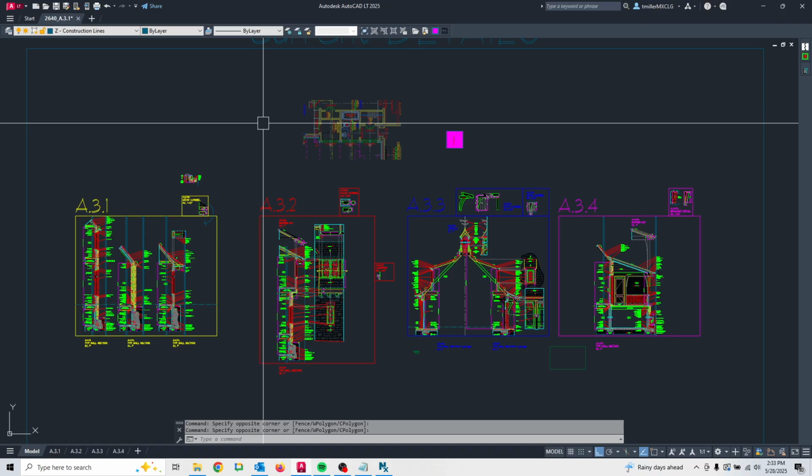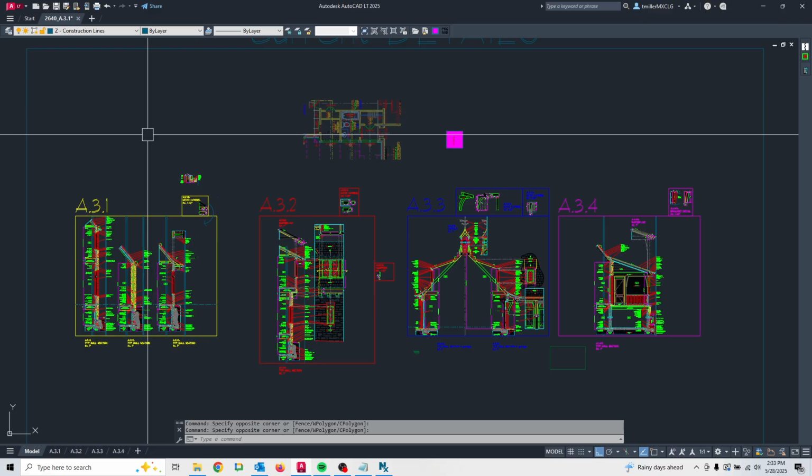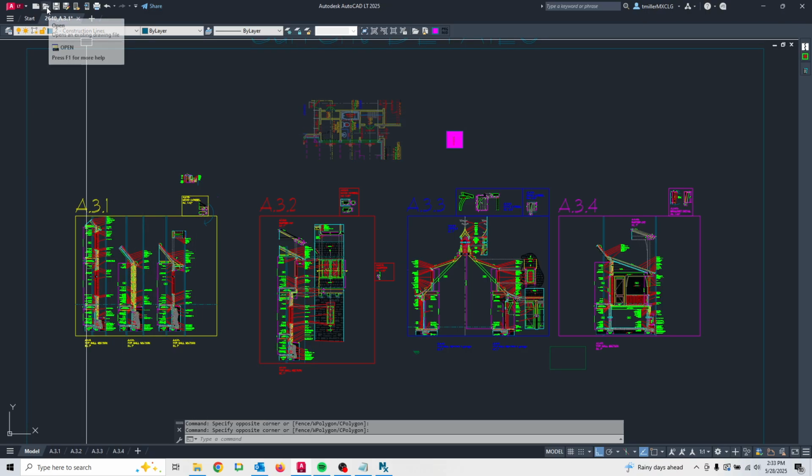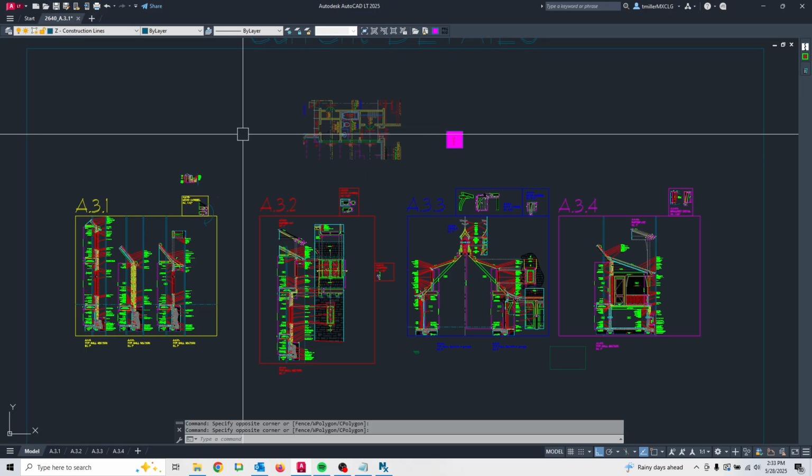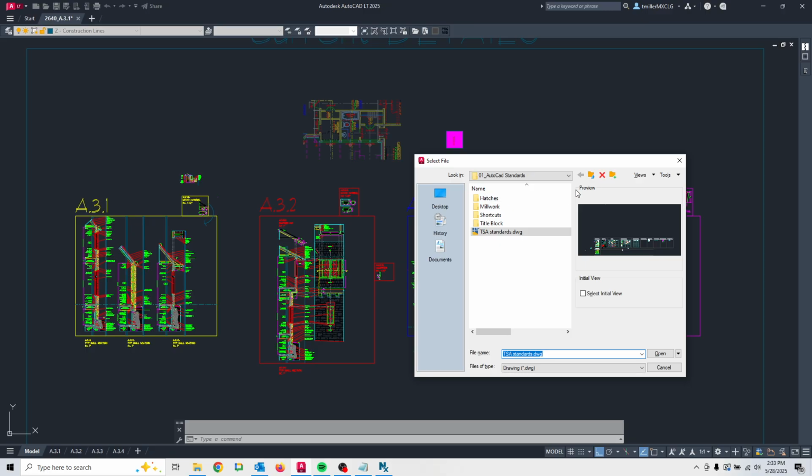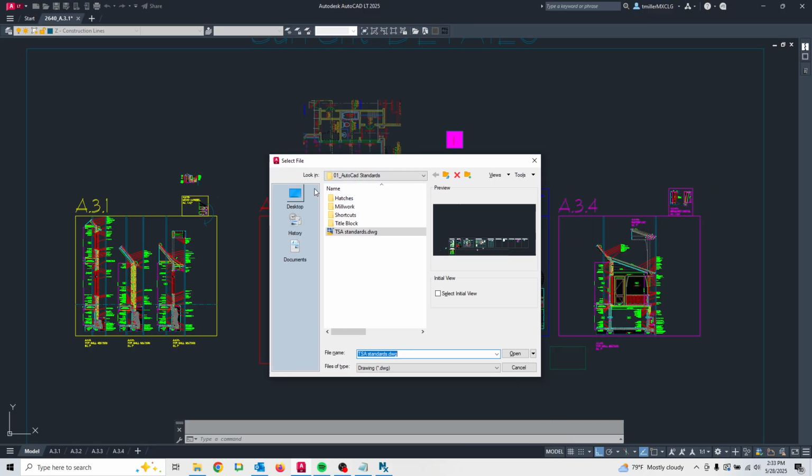What we're going to start with is within AutoCAD, the Open Files window has this panel. Typically, to access a job, we would click this open button, or I would recommend, if you can, always use a keyboard shortcut rather than a mouse button whenever possible. It tends to be more efficient. So Control O will open this, and then we've got this panel over here that we can customize.